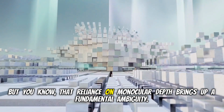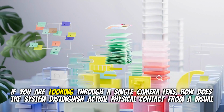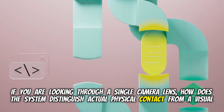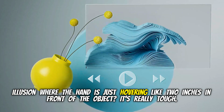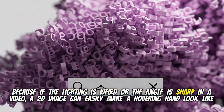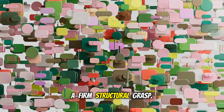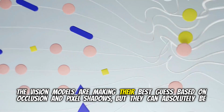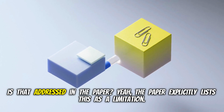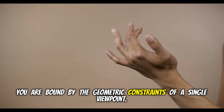But that reliance on monocular depth brings up a fundamental ambiguity. The hovering problem. Yeah. If you are looking through a single camera lens, how does the system distinguish actual physical contact from a visual illusion where the hand is just hovering like 2 inches in front of the object? It's really tough. Because if the lighting is weird or the angle is sharp in a video, a 2D image can easily make a hovering hand look like a firm structural grasp. Right. The vision models are making their best guess based on occlusion and pixel shadows, but they can absolutely be wrong. Is that addressed in the paper? Yeah, the paper explicitly lists this as a limitation. You are bound by the geometric constraints of a single viewpoint.